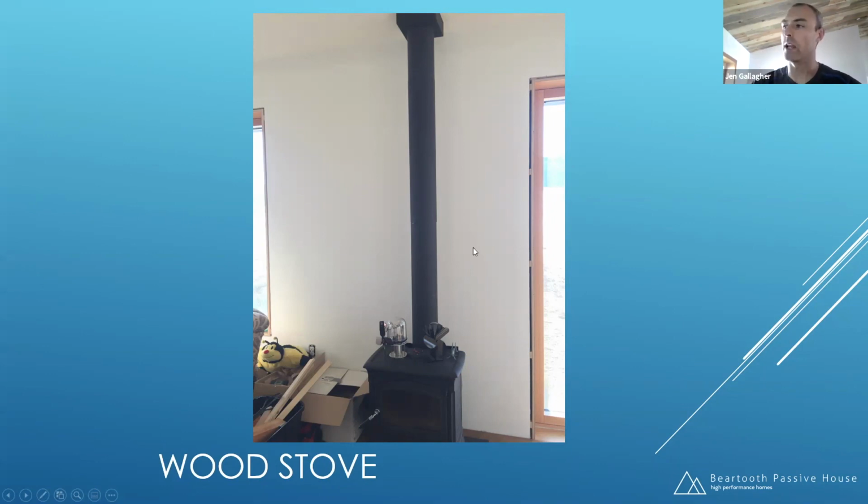So knowing that, I wanted to keep this joint mobile. Now this joint right here and this little joint right here, I just put black high temperature silicone around it. Like I said, I'm comfortable doing that because the same black high temperature silicone was used and recommended by the manufacturer to attach stuff to the backside of this stove.